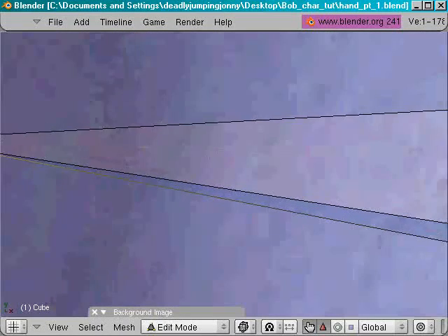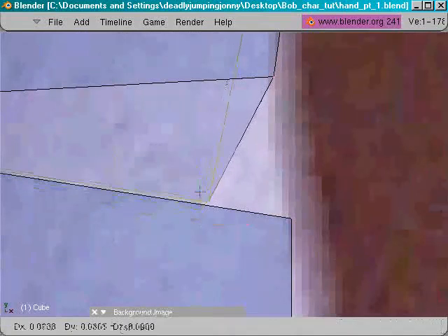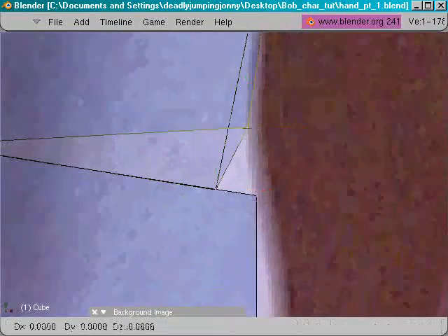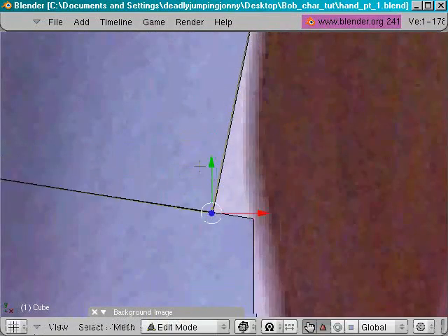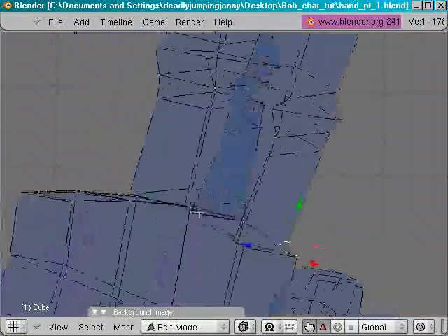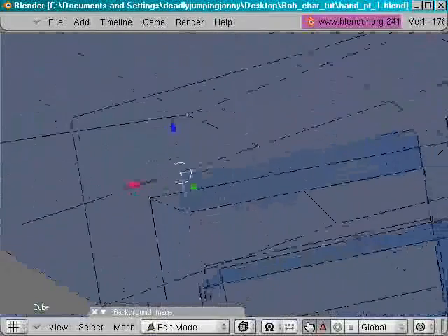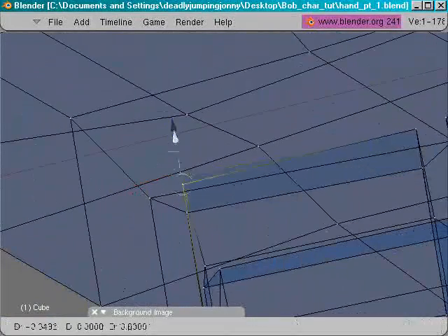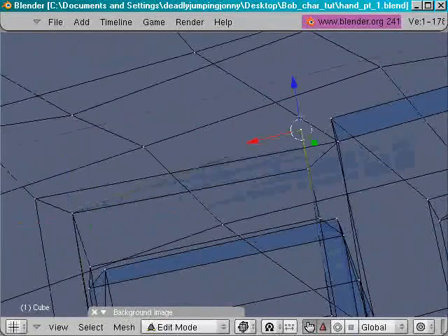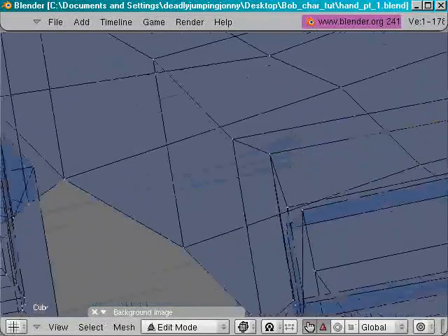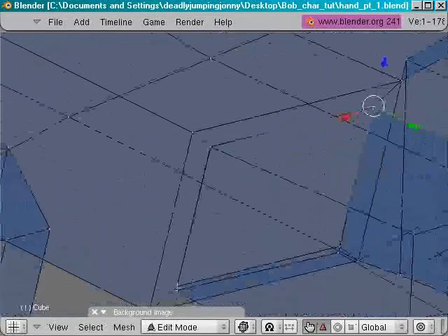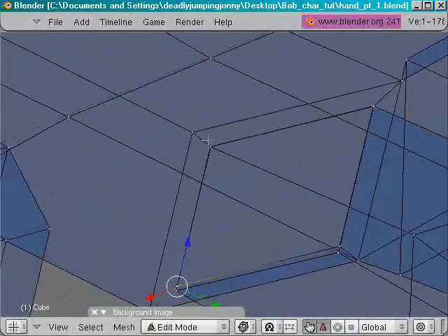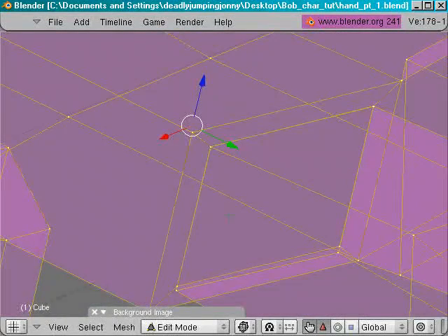And what we're going to do is just remove the doubles, and that will create a nice closed mesh for us. We'll probably have to put up the limit. See, look, yeah, that's a bit too high, really. And just move it down. Very easy. It's not quite... We might be able to get away with that if we raise the limits somewhat.